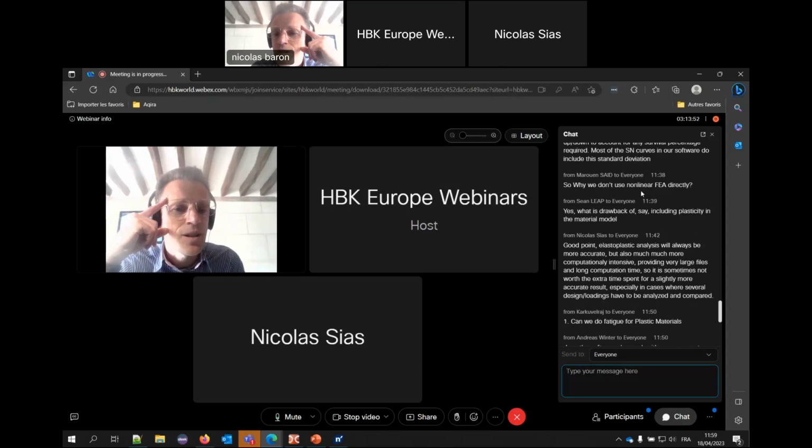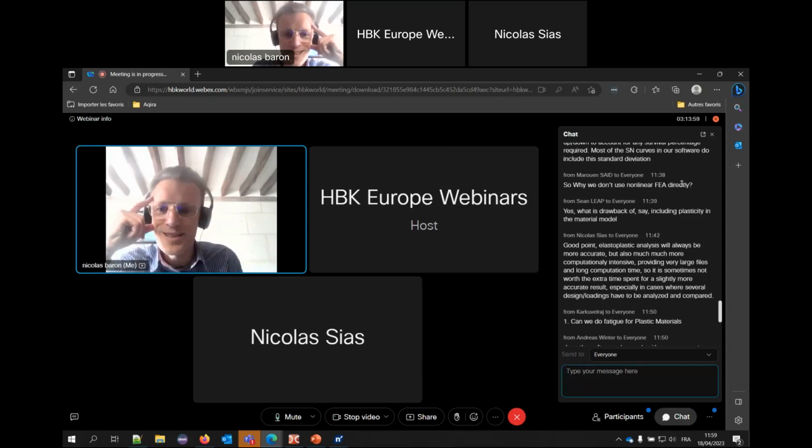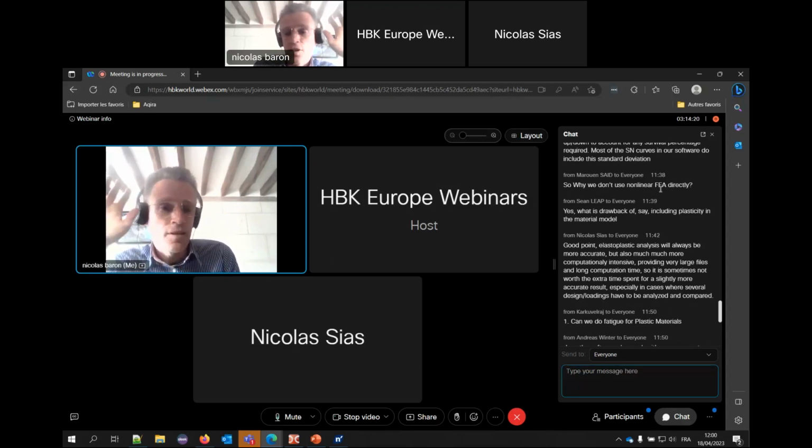Someone is asking, why don't we use nonlinear FEA directly? Well, you could. That's no problem. It's just that it's more involved, and you have to be really knowledgeable in what you're doing in terms of structural calculation if you want to have nonlinear calculation. But if there is a formulation of your material nonlinear or for high deformation, large displacement, that's okay. You're not constrained to do linear calculation with the software. You can do any kind of calculation you want in your software and bring that into Design Lab. What we highlighted with numbers was just a way to simplify your life. If that is valid, do the calculation simply linearly and then take into account non-linearity using some corrective tools. That's the only thing.